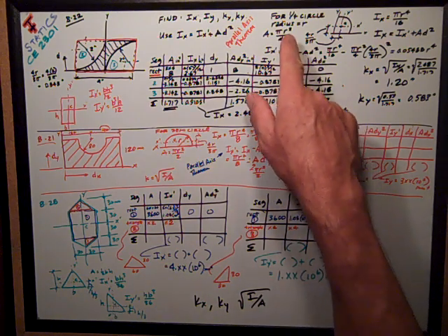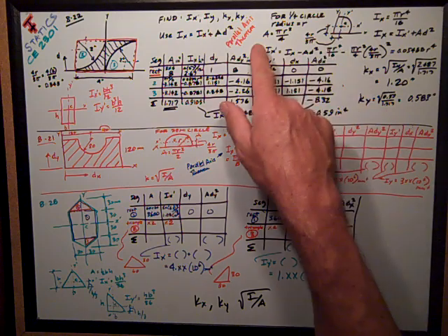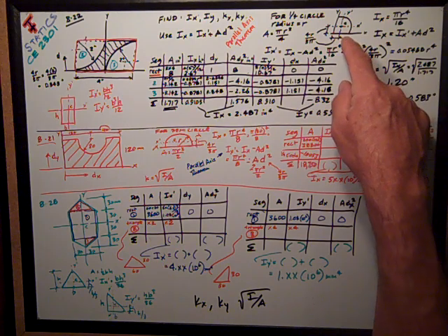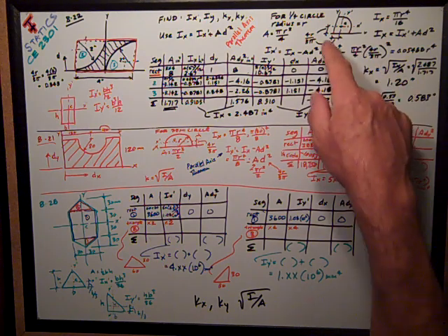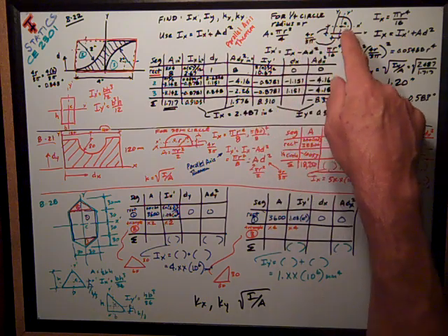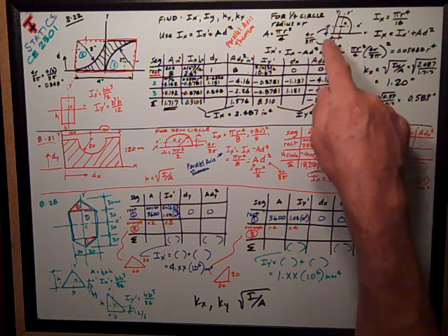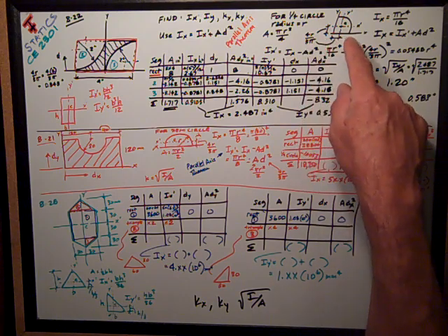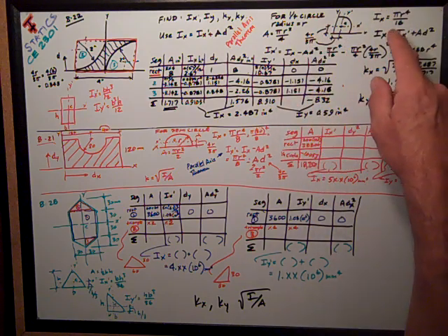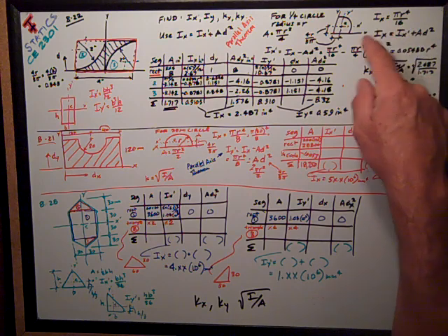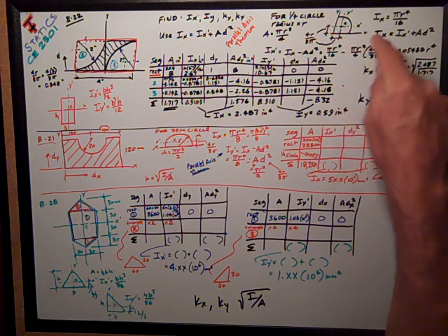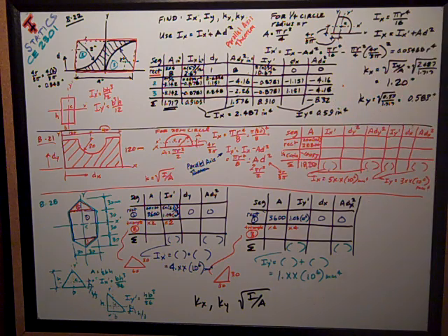So first we talk about a quarter circle, the radius of r. The area is of course pi r squared over 4. And we can get from formula books and off the internet and textbooks that the centroid of that quarter circle, measured from one of the flat sides, is 4r over 3 pi. Of course, being symmetric, it's the same to the y and the x-axis. And we can also get the formula that Ix, the moment of inertia of that shape about the x-axis, not about its own centroid, but about the x-axis, is pi r to the 4th over 16.